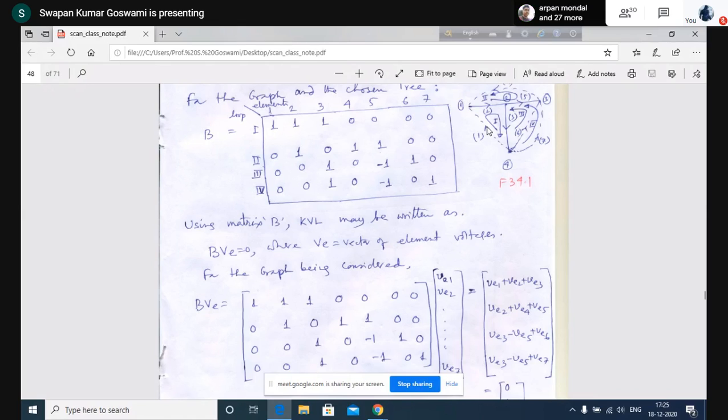Now, loops are not identified in that way. How have we identified the loops? By seeing the direction of the element that becomes the link forming the loop. Therefore, now you see that in the common impedance between loop 1 and loop 3 and also loop 4, the loop currents here are all in the same direction. So obviously there will not be a negative sign. It will no longer be negative, rather it will be a positive impedance.